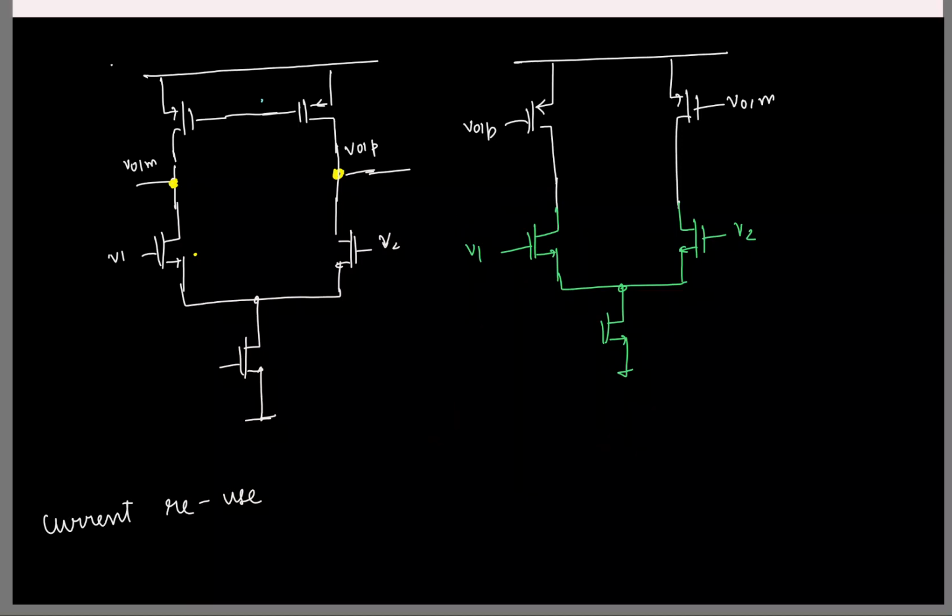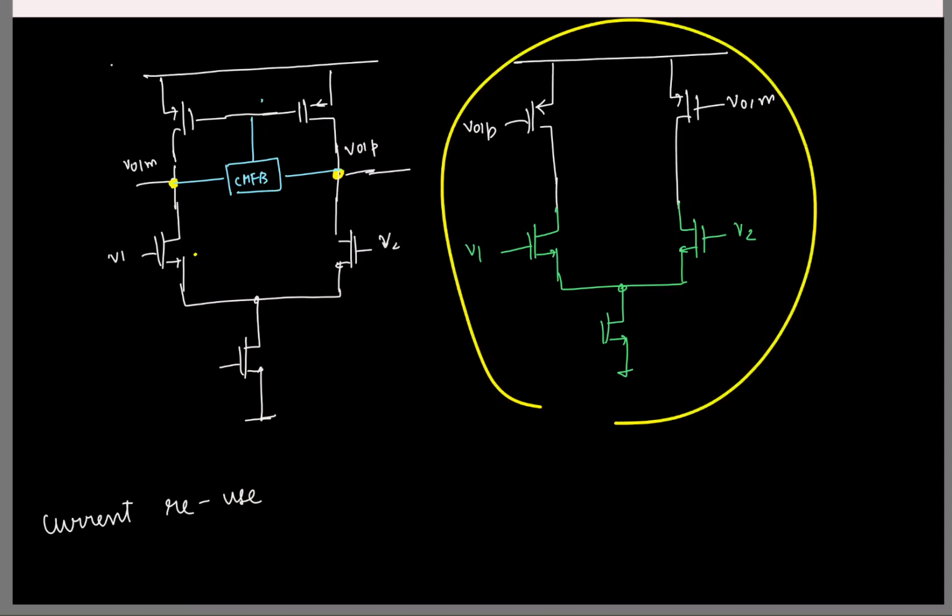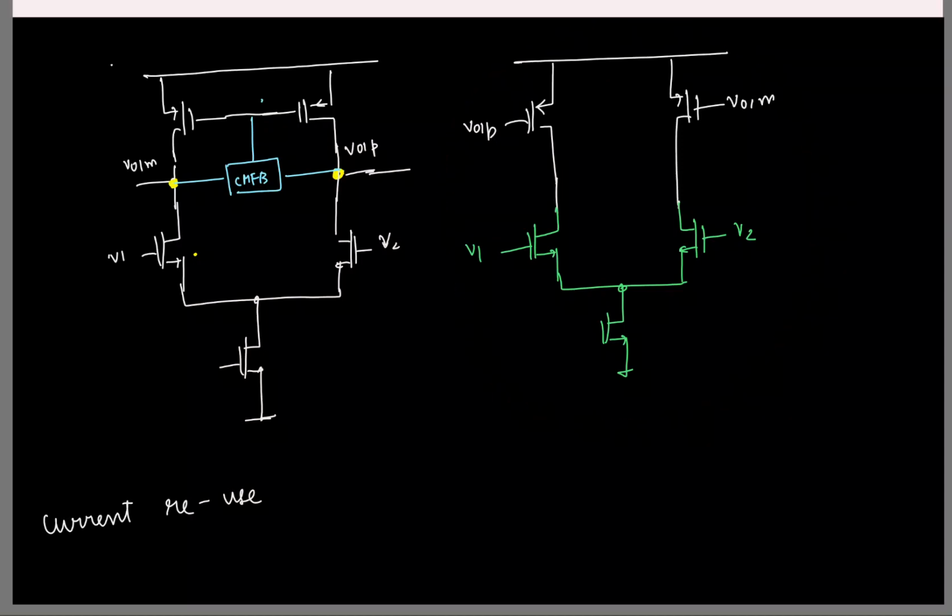So now we'll have to do common mode feedback. So again, for the first stage, I'll put a CMFB. We saw what kind of configurations will be fine. The same things we saw for Miller op-amp will work. So similarly for the second stage, I'll have to do one more CMFB. Okay. So one thing to notice, see, in the first stage, I could actually control either this current source or this current source. Either of them will work. Okay. Now in this second and third stage combined, I have again two current sources, this guy and this guy. What is setting the current in the NMOS here?